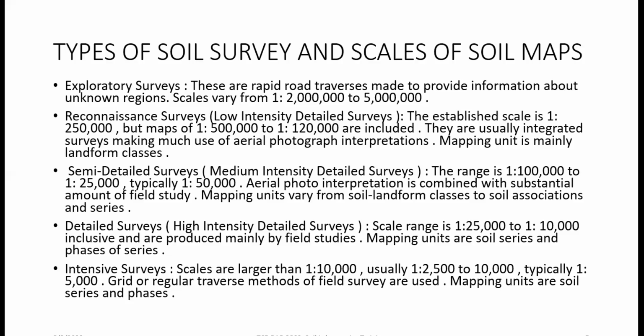There is the exploratory survey, and normally this one is a rapid road traverse mode. You just want to know information. For example, if I have the chance to come to Lebanon, during my drive from the airport to, for instance, Tel El Amara, when I am in the car, I can take some notes on how far the soil in general is different.